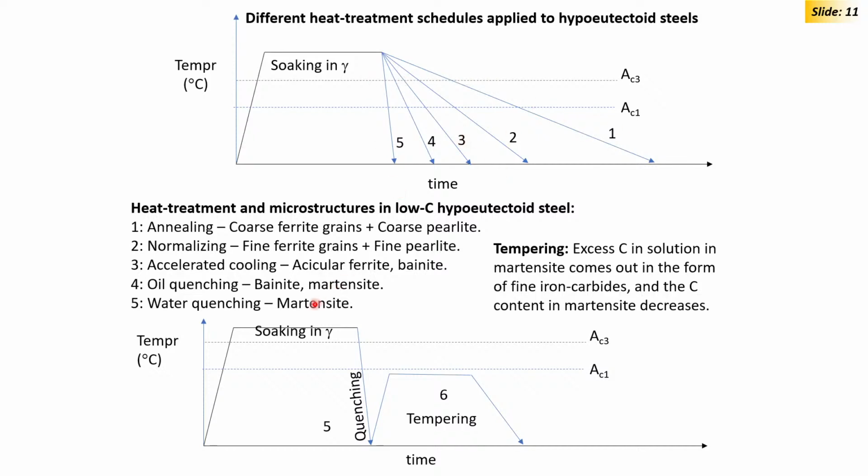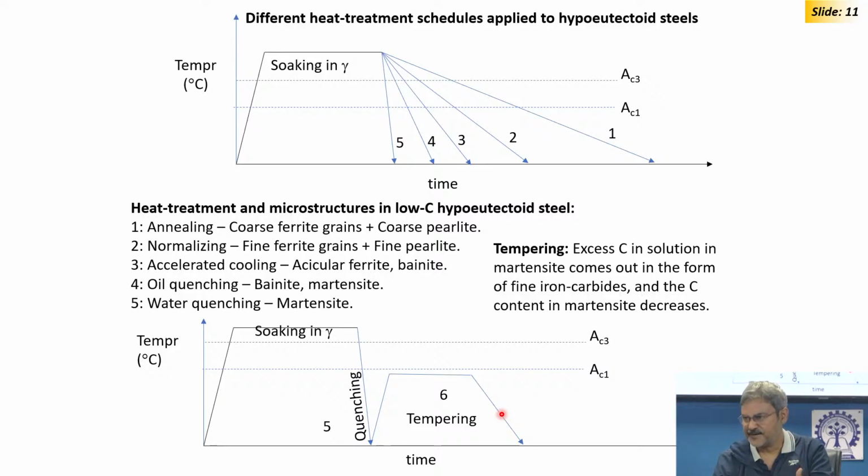Even faster quenching, we tend to get martensite, and we prefer to temper martensite to soften it, so that it gains some ductility, otherwise martensite has poor ductility. So, the question is where all these phases are coming from. So far we have talked about diffusional transformation and displacive transformation without any atomic partitioning, and we now try to understand more about the displacive transformations.